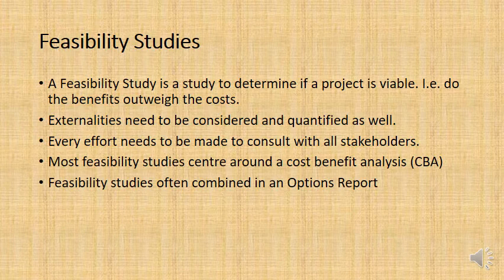Now, a feasibility study is basically a study into a potential piece of civil engineering infrastructure to see if we should go ahead with it, should we build it or not. Now, I think a very important thing to know is with the word feasibility, we often have the view, is it possible? Is it a study to see if the civil engineering project is possible? Well, that's not what a feasibility study actually entails, because anything is possible.